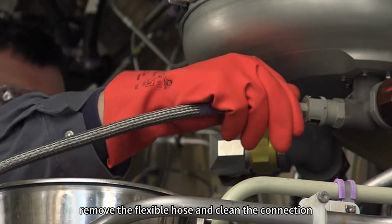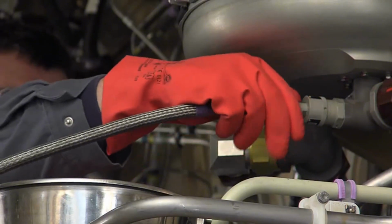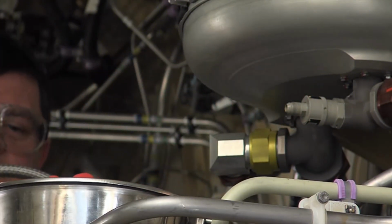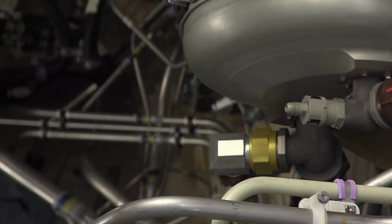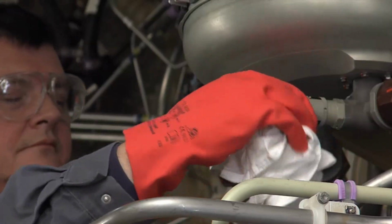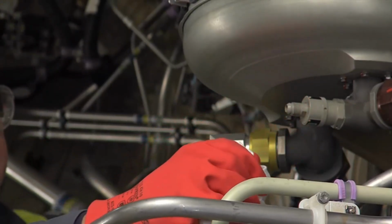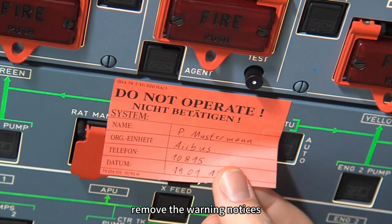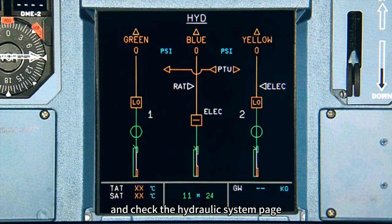Remove the flexible hose and clean the connection. Repressurize the reservoir before operation of the system. Remove the warning notices and check the hydraulic system page for correct level indication.